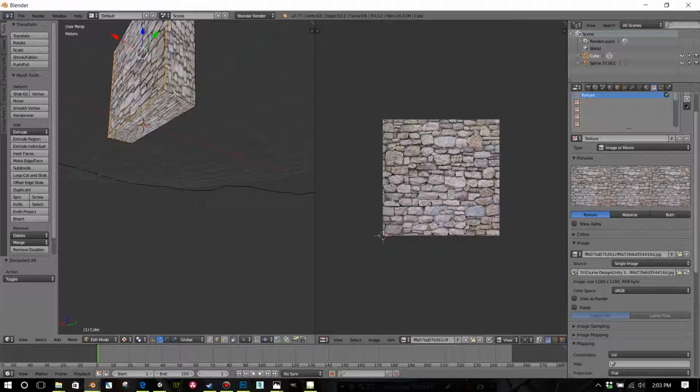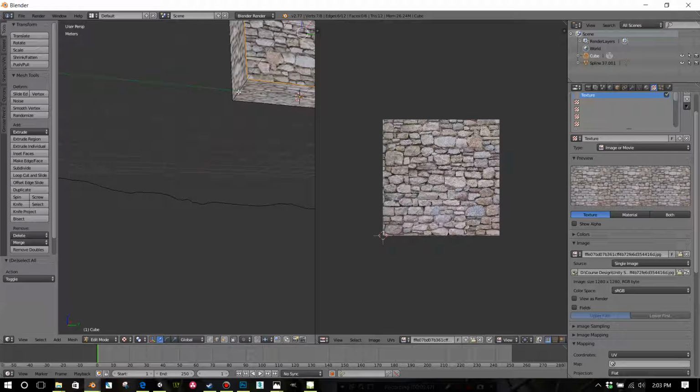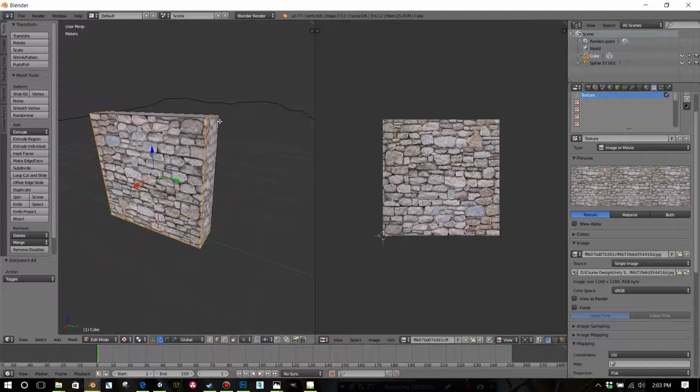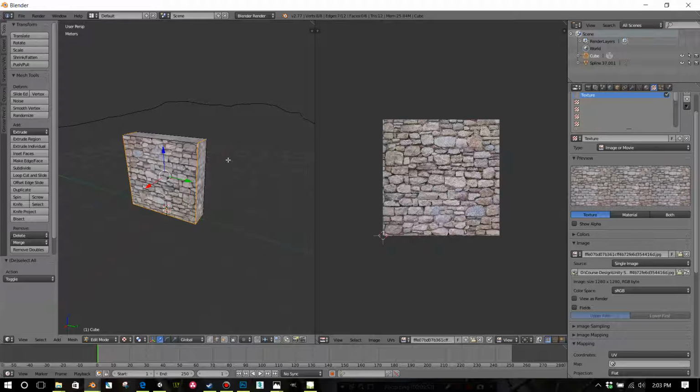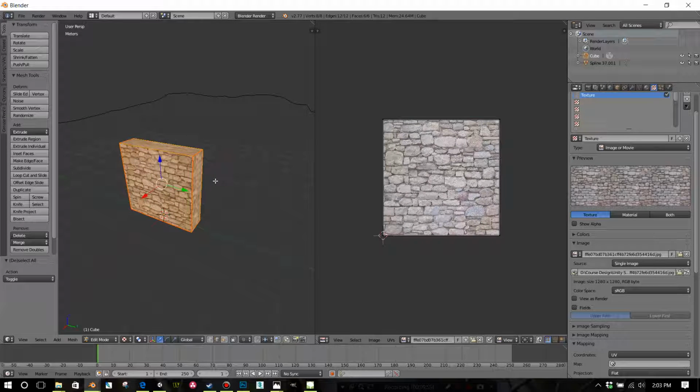Right now this wouldn't be able to lay flat, so you've got to pick that edge there. This is kind of the fussy part. Unwrapping is always the pain for everyone. All right, now we've got our edges all selected, and I'm going to hit Control E, mark seam. Now you can see it's going to mark them in red. Then A to select the whole thing, and then U to unwrap.